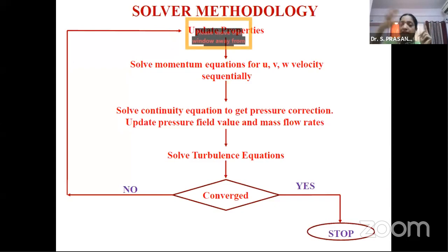For solid, as I told you, you need to initialize the material properties through which the flow is taking place. There you can give aluminium, wood, or certain parameters are already available by default. You can check, or select from them, or even initialize your own material by means of a user defined function. You can give your own material. Probably you have all the properties like temperature, density, and thermal coefficient. These are some properties that are required in order to initialize your own user defined function.